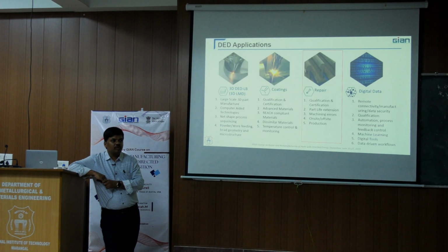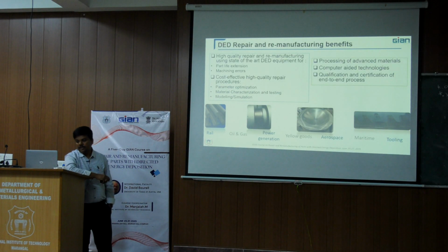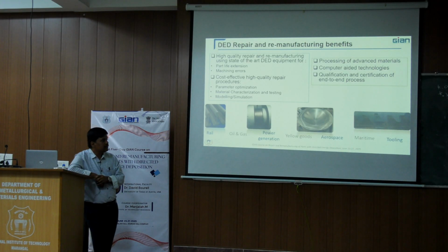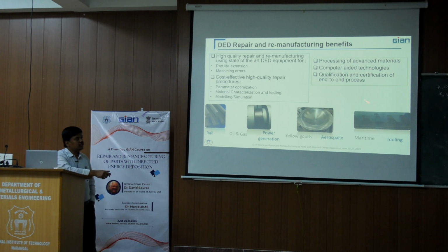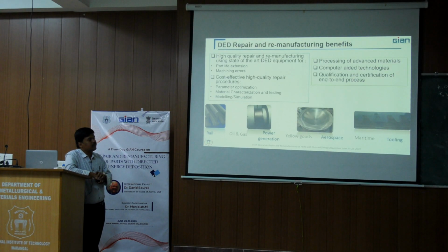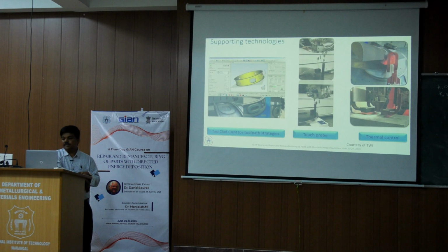To address these things, we have to do a lot of experimentation. That's what we have attempted. One of the aspects is rail components, oil and gas industry components, or maybe tooling industry components where a tooth has broken. This is where we can use the DED process in a very cost-effective way to qualify components for repairing. But for these aspects, we need to understand what supporting technologies exist.